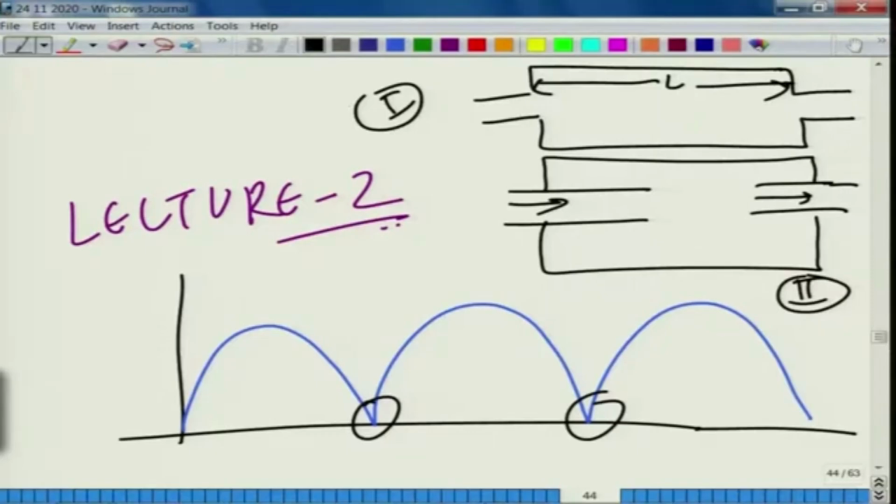In such a chamber, the inlet and outlet ports are protruded or extended inside the chamber with a view to generate peaks at certain frequencies, such that they coincide with the natural frequencies of the overall chamber. When that happens, the troughs are cancelled by the attenuation peaks, and the overall transmission loss performance would be enhanced.